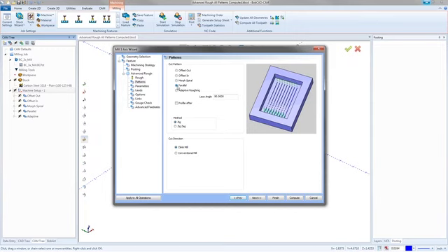Now, when you're using the parallel, you have the lace angle as well. So the lace angle allows you to change what direction it's going in. 90 degrees is always going to be along the Y. 0 will always be along the X. You can use any angle you want. That's just how it's going to line up. So if 0 is along the X or the 3 o'clock position, if you did 85, you'd be at 85 degrees between that X0 and the Y90.